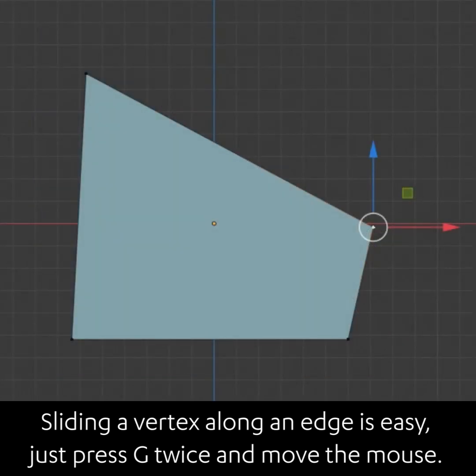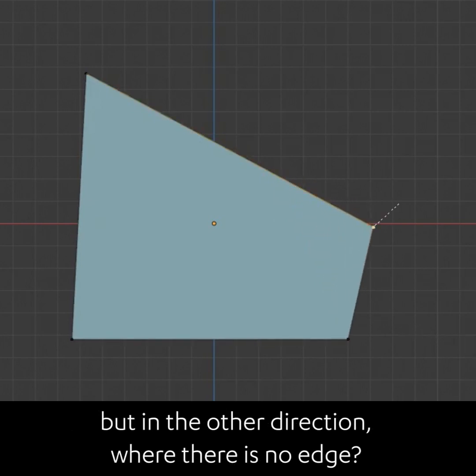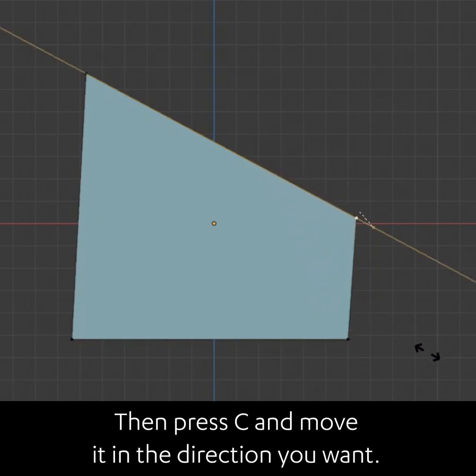Sliding a vertex along an edge is easy. Just press G twice and move the mouse. But what if you want to move it along the same angle but in the other direction where there is no edge? Start the same way by pressing G twice and sliding the vertex in one direction of the edge. Then press C and move it in the direction you want.